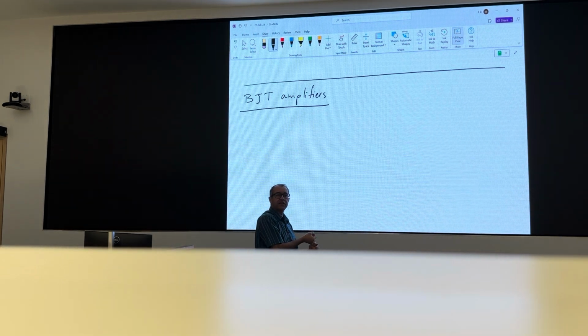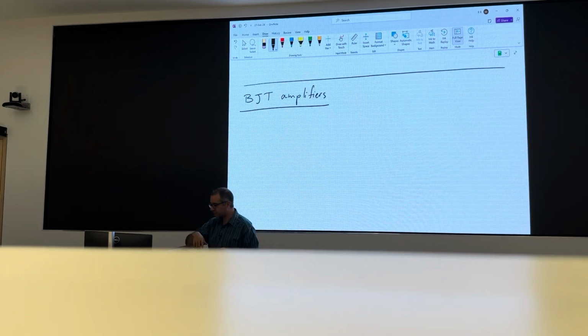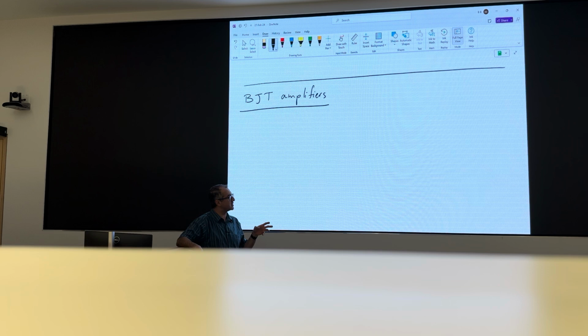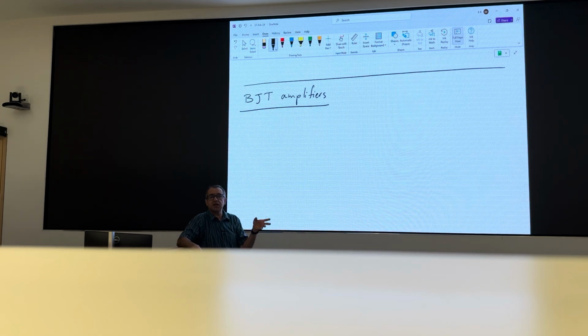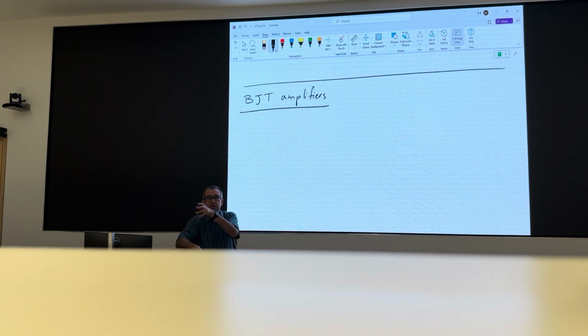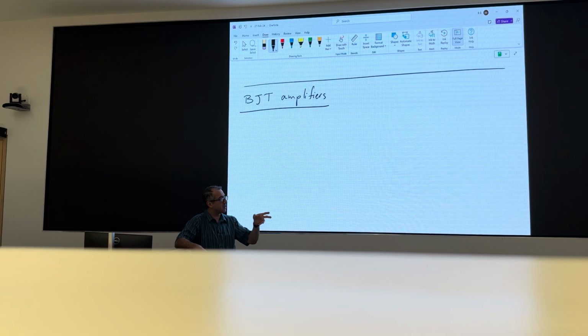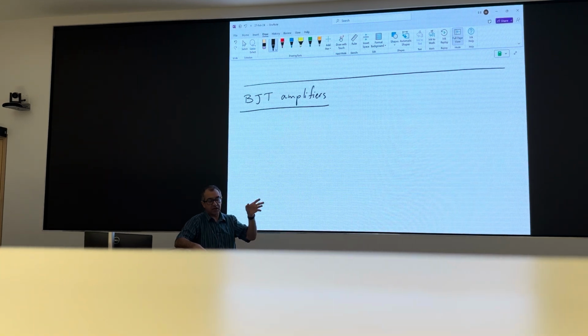If you want to make a filter, filters are usually passive devices in the most basic form. But the problem with a passive circuit is that your signal becomes weaker and weaker as it goes through it. So usually a filter also has an embedded amplifier in it. You can have active or passive filters, both are doable, but in many cases you use active filters.